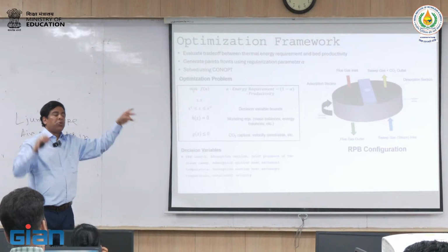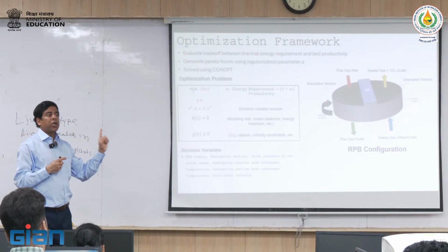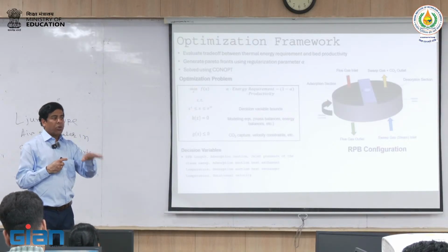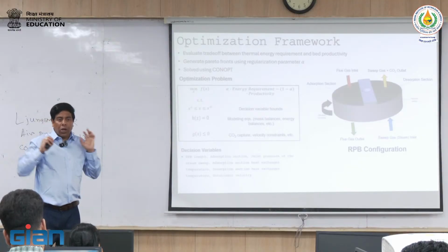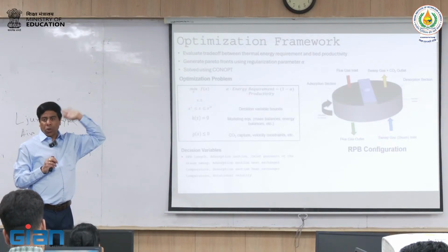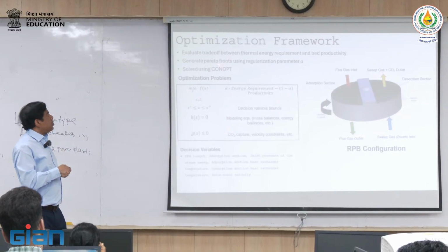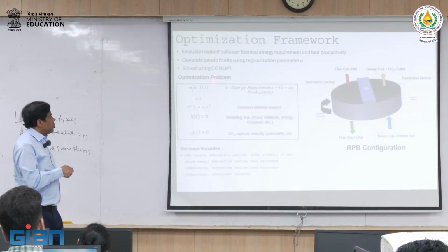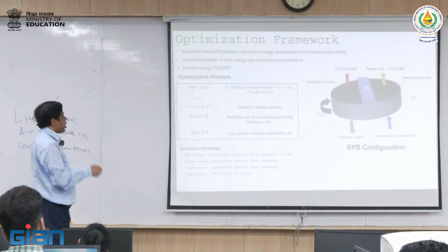And there are multiple different ways we did this. We created an initial guess by, in ACM we had difficulty in solving this, so we first did a dynamic problem. We said we start out with something and let's solve a dynamic problem that generates a good initial guess. When the dynamics settle down, that means these boundaries have settled down. Then you grab that snapshot and load it as a steady state, and then you design this. So in Aspen, this is what we did. But this could be done in Python.